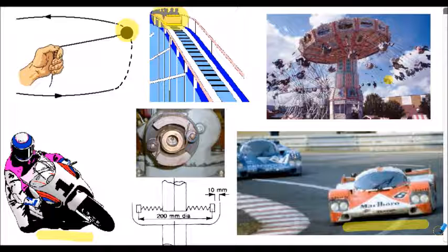For example, we have centrifugal casting processes, there are centrifuge facilities for testing purposes, there are centrifugal clutches in small motorbikes or mopeds, shown here. These are masses with friction surfaces on, attached by springs. Illustrated diagrammatically here. Here's a mass. Here are the springs attached to the shaft. So as the shaft rotates, we can consider the masses to be pulled outwards by centrifugal forces, so we can analyse movement of the friction surfaces.